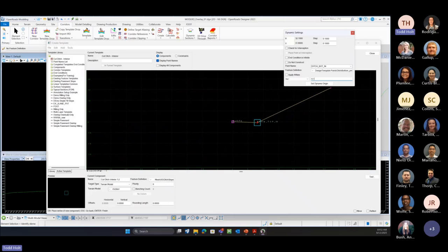So we're going to go 1 and then semicolon 3. So we're going to go 1 foot over, 3 foot down. That's going to be our ditch bottom in. And here, we want it to go down, so we need a negative 1 to 3. We could fix that if we needed to, but we're going to go 6 and then comma negative 1 to 3. We'll hit enter.